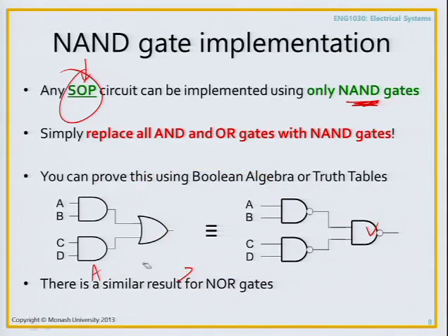So you've gone through and designed your circuit to do something in particular. It might be you've designed it to add two numbers together. You've got a lot of AND gates and OR gates. Well, you now want to implement this in a chip. You just need to program on the chip where the connections are between all these NAND gates, because the chip that you've bought only has NAND gates on it. So that's why you would want to do this.